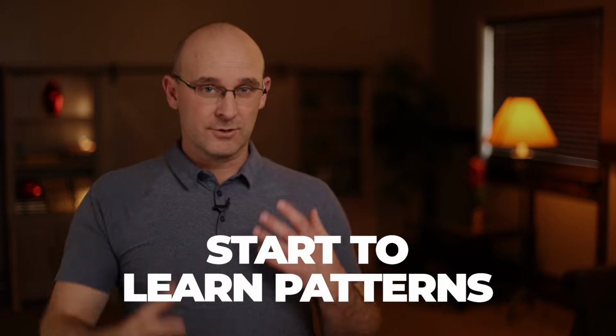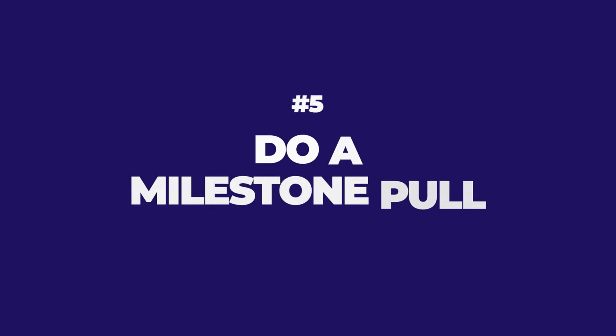So you start to learn patterns. You're like, okay, this is what has to happen in the floor. This is what has to happen with the electrical rooms. This is what has to happen with the chases. This is when we need to connect the underground utilities. So start looking for patterns. One of the best ways to do this is to do an overall milestone pull plan, where you look at the systems generally and you interconnect them in a sequence for how they're going to get installed with the trade partners. It's super scary, but once you have that backbone put together, you're going to be jamming and you're going to have a high level understanding of how to build that building.